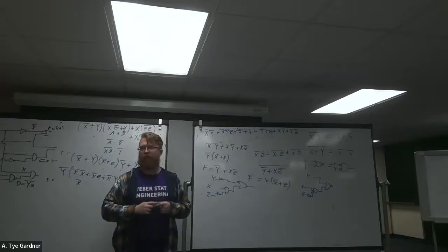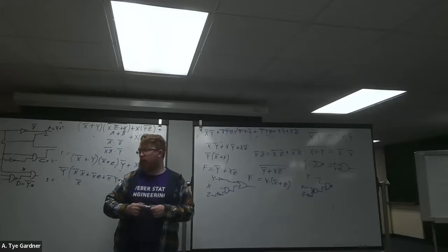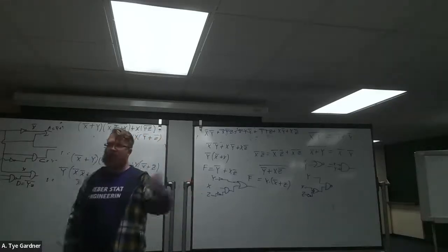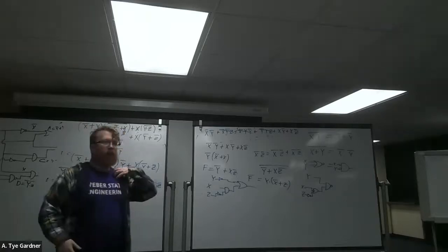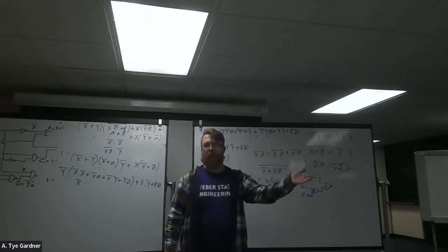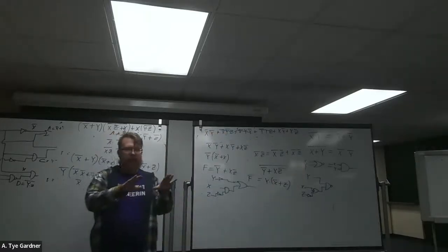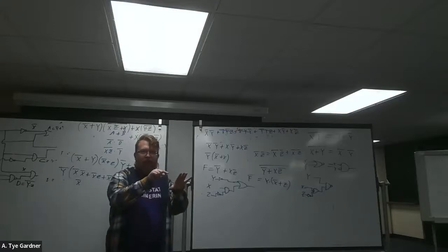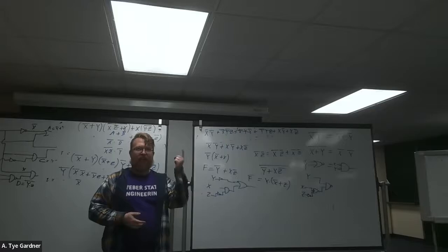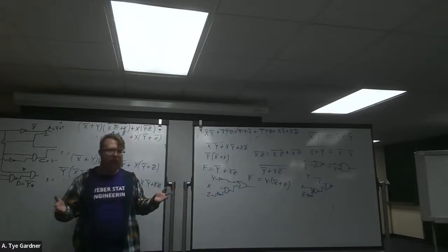But what's the value in changing it from a NOR to a NAND? The benefit is that depending on your technology, you may have one or the other. The most obvious example is if you were designing a chip and you needed some memory on it. You would go out and buy memory, and it's going to be either NAND flash or NOR flash. Each of those has different benefits. There are trade-offs between the two.